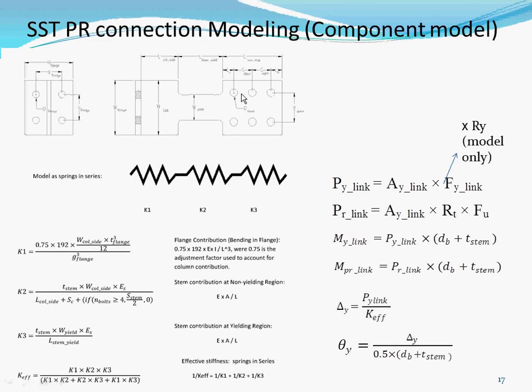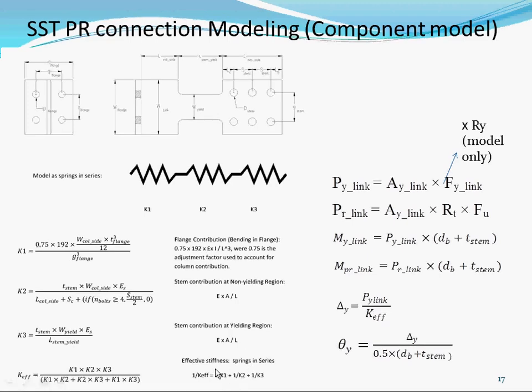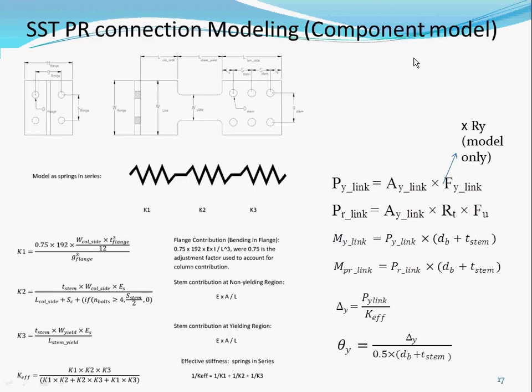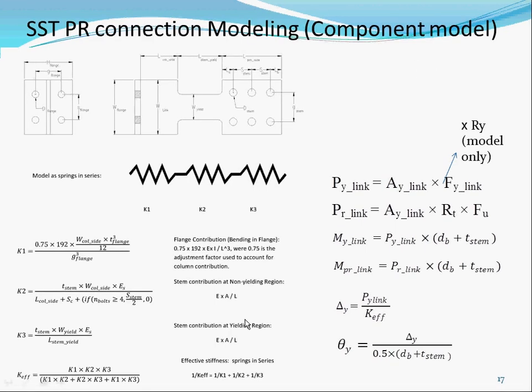So, knowing just the geometry, you don't need anything else. Just knowing the geometry, we could figure out an effective stiffness for the connection. So no fitting of the C or the N is required if you do it this way. This component model has been used in the EC code for a lot of their connections. So if you're familiar with that, that's what they adapt for that.